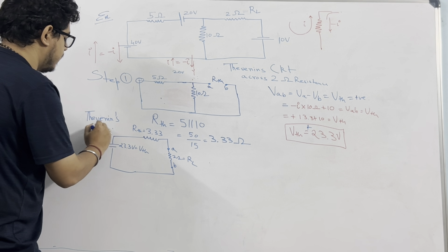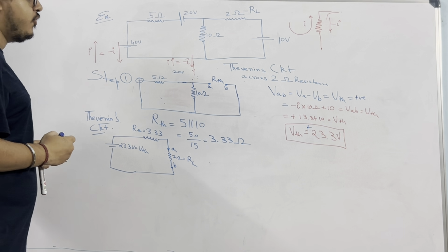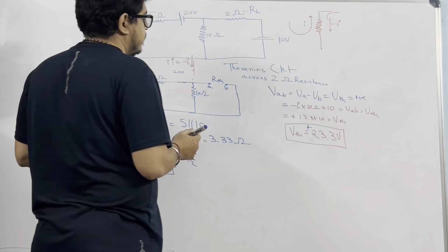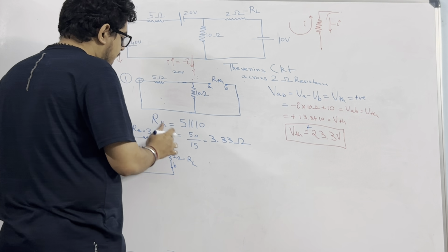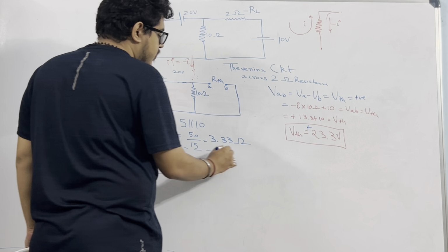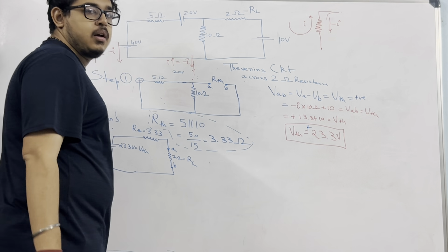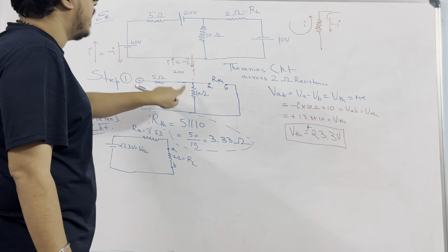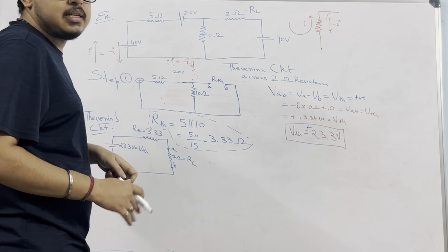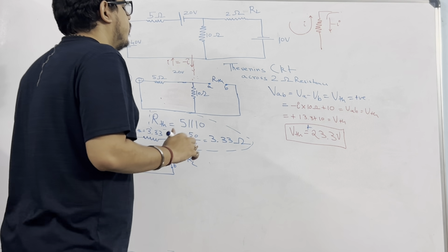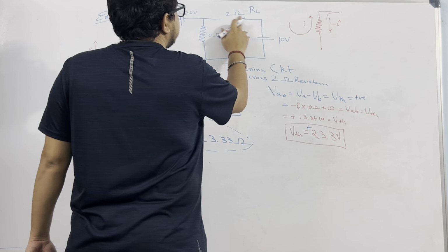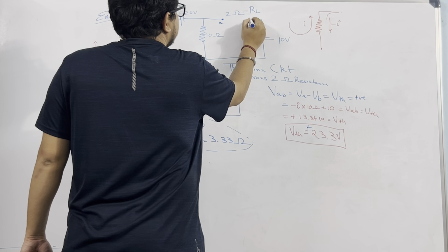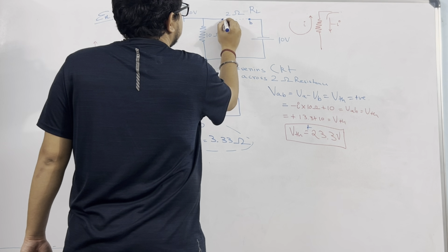circuit reduction. Okay. Now I want you all to know one more way of finding RTH. It will be very useful when dependent sources come. If suppose you are not able to solve, it was very easy, R1 parallel to R2. If some complex circuit is there, what you can do is, suppose you remove this and make it A B. You make it short circuit. Okay, like this.